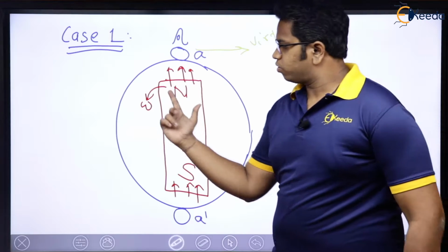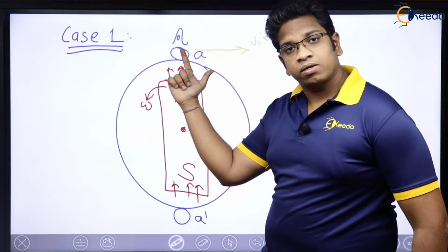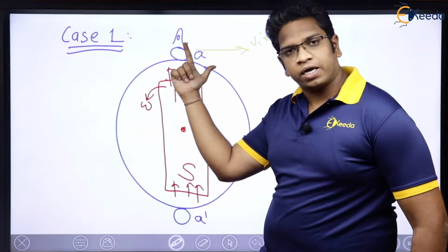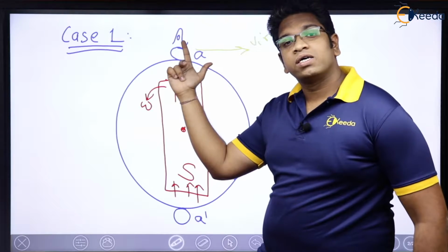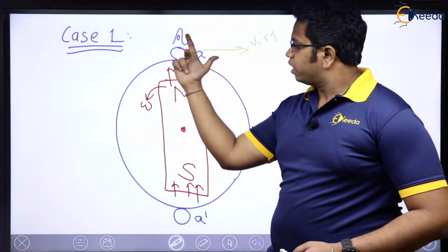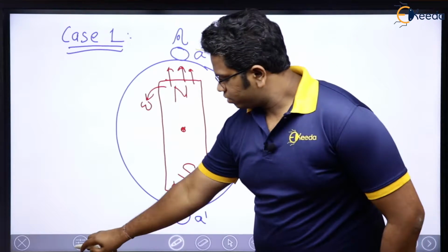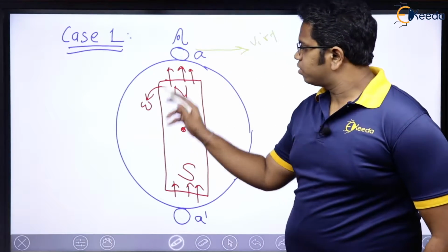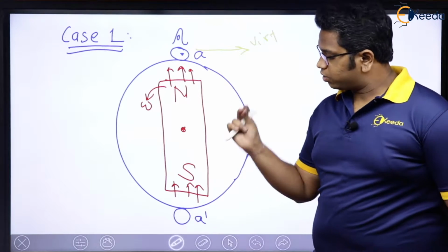So see here, this is going to be the flux, right? This is going to be the direction of the motion of conductor, and my middle finger will now be showing what? Induced EMF. So it is coming out of the board, which means it has to be placed by a dot. Let me have a dot here. Is it perfect?